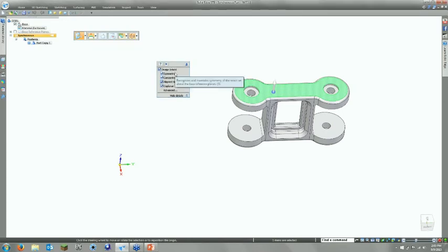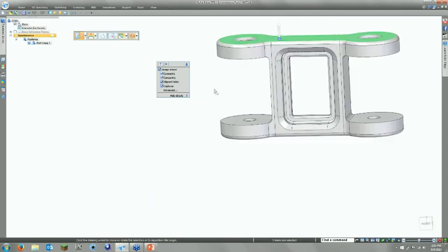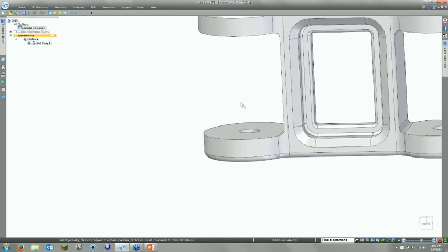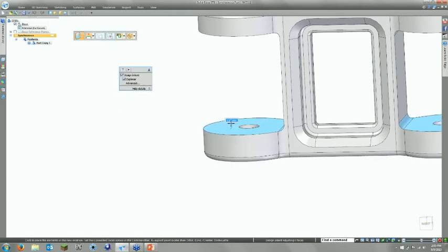Every single time you do a modification in Solid Edge Synchronous, it interrogates the geometry looking for design intent. So they simplified the interface, allowing you to see immediately what's going to be picked up as design intent when you start making a change. For example, if I pick a face, it gives me your common list of concentrics and metric, but when I start dragging this, you notice it only shows me coplanar.